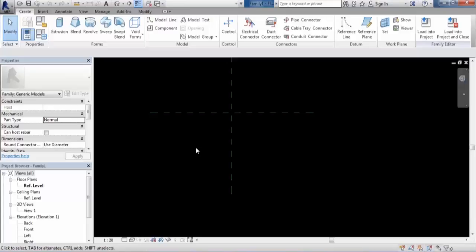Similar kinds of thing, because the family is the 3D model. So I will try to make one 3D model, but in the CAD you cannot control the parameters of the 3D models, but in the Revit you can control the parameters. Suppose I need one 200 by 200 by 300 box. Then I will create parameters height, width, and length, and accordingly I will make one box,